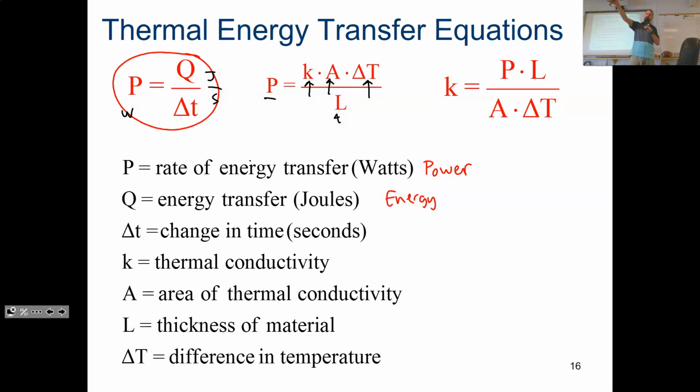If it's really, really cold outside, we're definitely going to lose energy faster. So it depends on those four things: what the wall's made out of, how big the wall is, how thick the wall is, and the temperature inside and outside. For instance, if it's 60 degrees outside and we have the thermostat set at 60 degrees inside, it doesn't matter how thick anything is, no energy is going to flow.